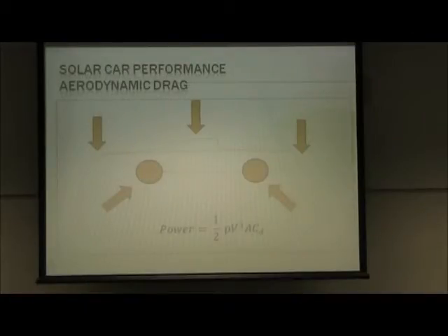That's where the drag is. There are some things you can do to reduce that, and jets and other things, but you concentrate on having a nose and going ideally 8 inches back at least, and having that as smooth as possible, polished. Same thing on the sides. Even those decals ought to be smooth, not decals sticking up.